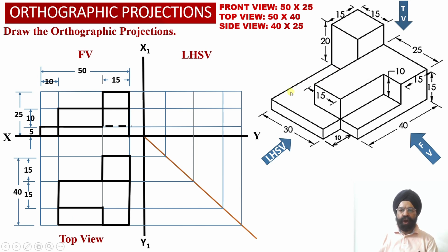And finally we have got element number 1 L-shaped surface available over here. So again this L-shaped web will be visible to the observer as a true shape projection into the top view projections, because this surface is once again parallel to the horizontal plane. So this way we have been able to obtain the top view projections of the solid onto the horizontal plane over here. Now let us obtain the left hand side view projections of the solid.